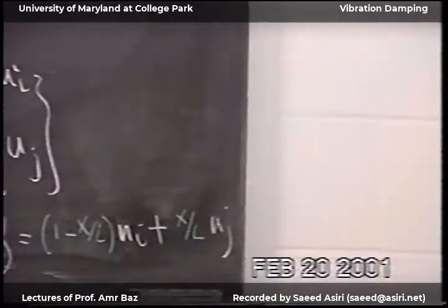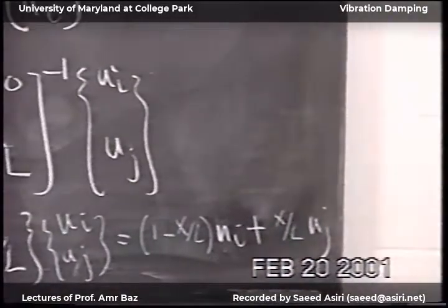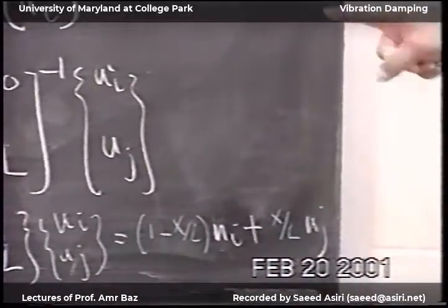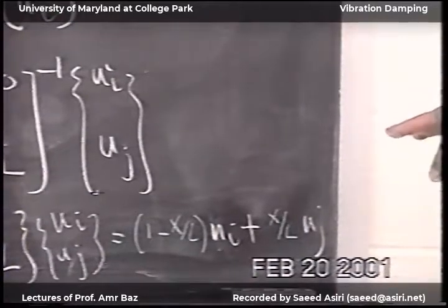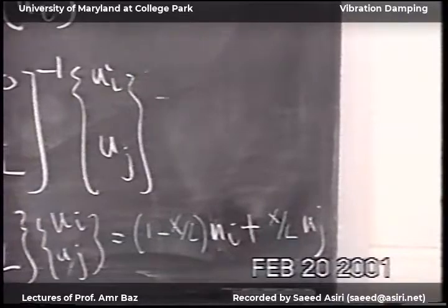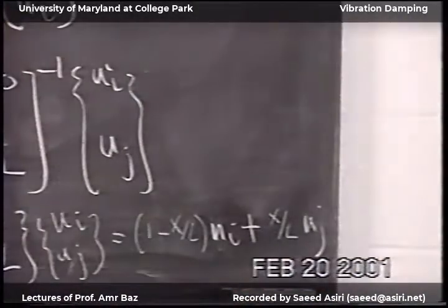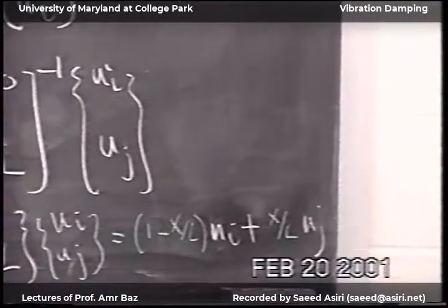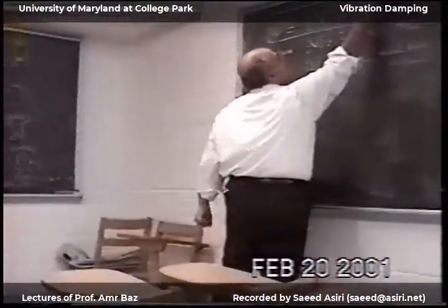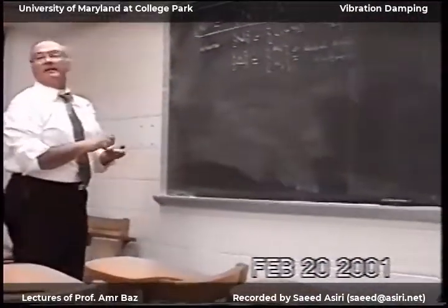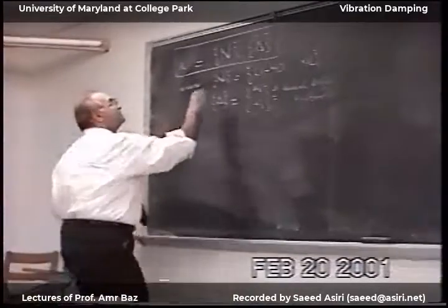And you could see here, if I put x is equal to 0, the second term will drop, and u will equal ui. When x is equal to L, the first term will drop, and the last term will be uj. Okay, so now this satisfies this. This is my equation for deriving the finite element. And the N will be my interpolating functions.